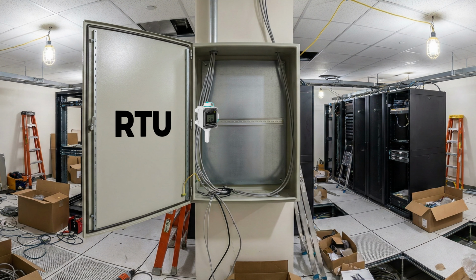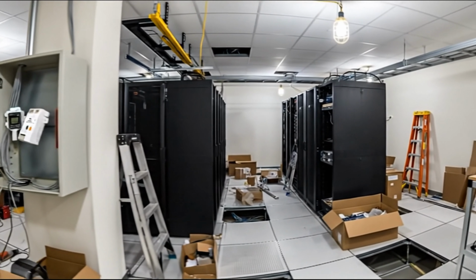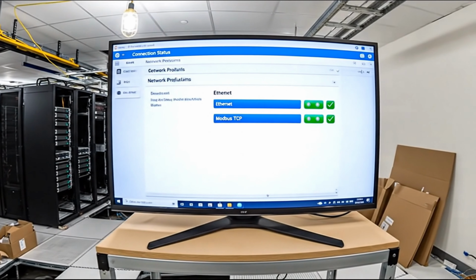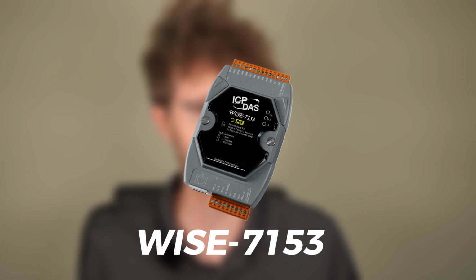Let's look at a common example. Imagine you're setting up monitoring for a server room. Your humidity sensors, your leak detection modules, or your power meters still use Modbus RTU, but your centralized software must connect via Ethernet. In that scenario, a Modbus gateway lets you pull all of that RTU data into one dashboard, set alarms, trend data, and expand later on without touching the wiring that already works. And if you also want that data to trigger automated responses, a controller like the Y series can take that Modbus information and act on it instantly.